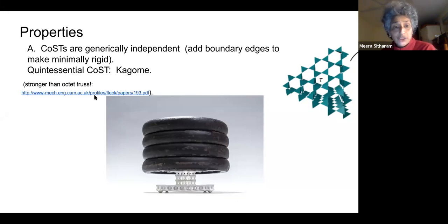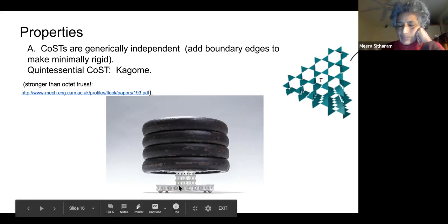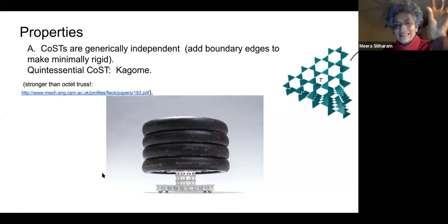And they showed that for the same amount of mass, it's stronger than the gold standard microstructure, which is called an octet truss. What we are essentially thinking about is to ensure that those properties, and these stress responses, can be analyzed using discrete rigidity techniques. Maybe not to the level of exactness that you might get from finite elements, but quick, extremely fast approximate computation from which you can do the design, and then later on do finer finite element computations.